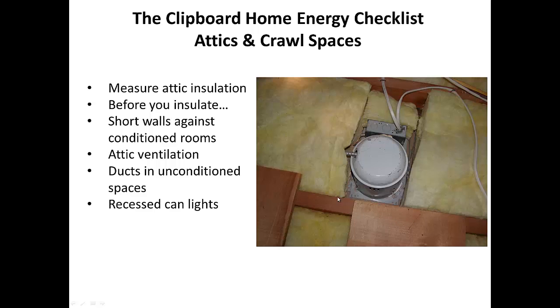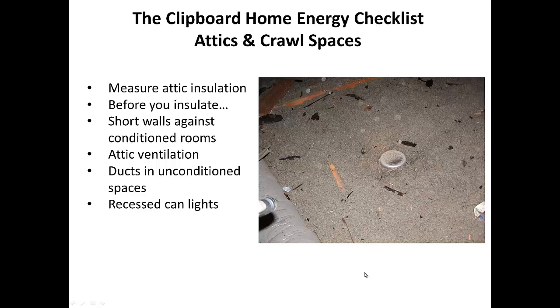Compact fluorescent light bulbs, CFLs, don't get nearly as hot, and certainly in general you want to take every light bulb in your house that's not a fluorescent and throw it away and start using compact fluorescent light bulbs. But here is an example where all these little holes are places where the heat just goes right up into the attic and out. Now there are things you can do for that that we'll see in a second, but here's another recessed light fixture that they haven't done a good job of keeping insulation away from, and that could present a fire hazard right there.